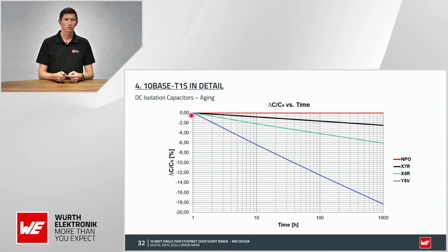After you power your circuit, several hours later or months later, you lose a little bit of capacitance. In the beginning, it is like 1% in 10 hours. But if you look at 100 hours or 1000 hours, it's more than 2%. And in most cases, you implement a circuit or a device, and then it runs for days or weeks. And this should also be taken into account.